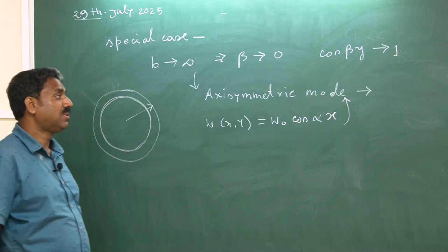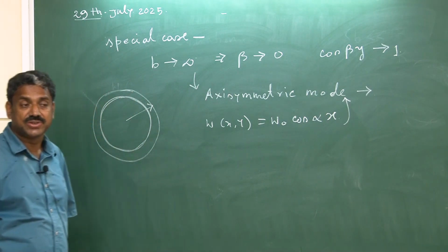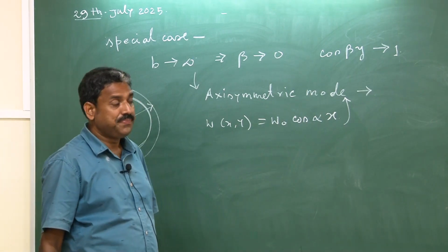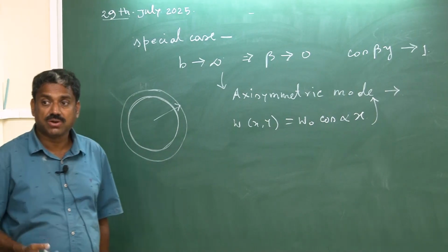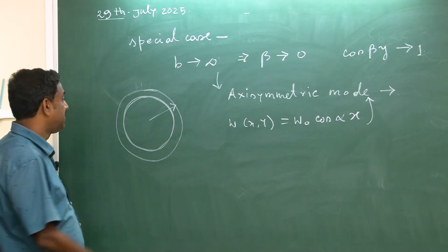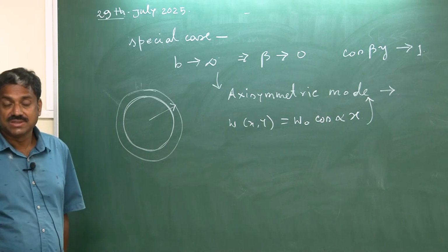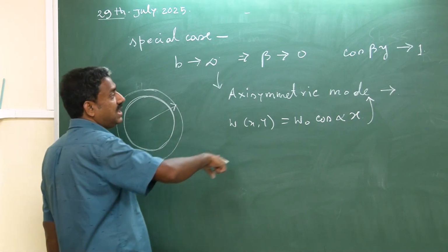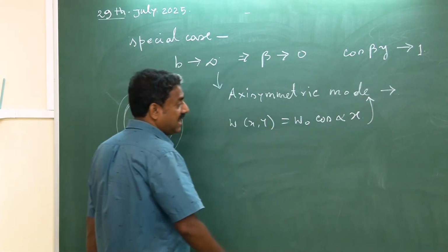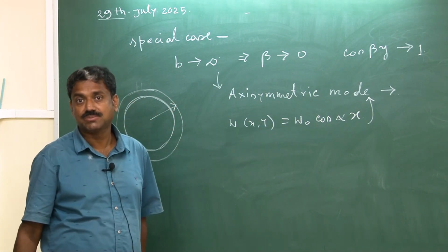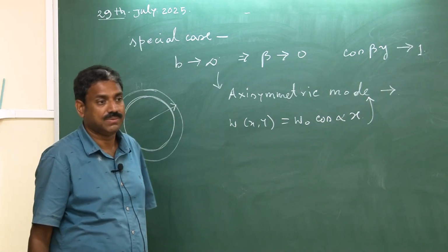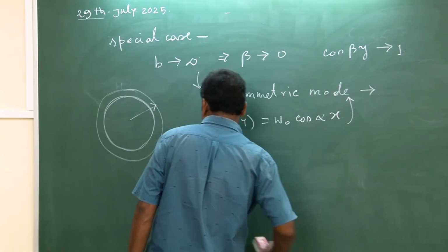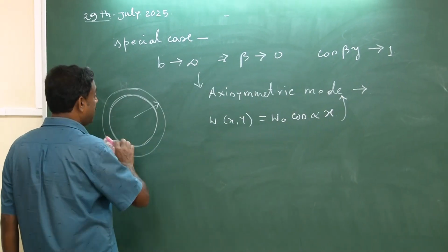So we see that Donnell's equation mimics, as a special case, axisymmetric buckling, where the circumferential dependence is not taken into account, assuming axisymmetry of deformation, and only a single mode is governing, the zeroth mode. That term dropped, and essentially that was a differential equation with x as the only independent variable, right. So with this, we can mimic that case.